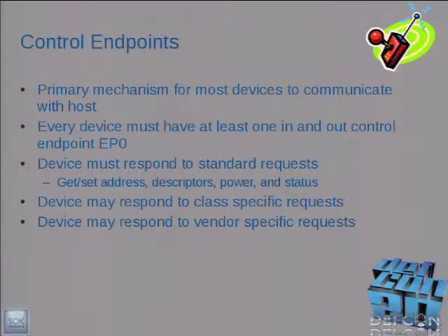So the devices can also respond to specific class requests for the class of device and optionally vendor requests. So you could in theory have a very special driver for your kind of mass storage device. In practicality, nobody does that because nobody wants to rewrite the drivers.